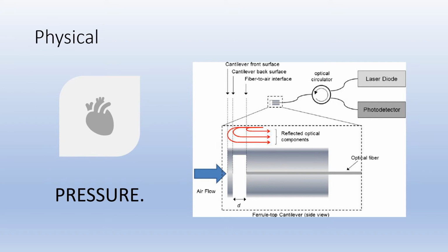The ratio of the light collected by the two fibers is sensed by the instrument, applying a feedback air pressure to the interior of the probe through a pneumatic connecting tube containing the optical fiber. With this knowledge, fiber optic transducers have been developed to monitor intracranial and intracardiac pressure.